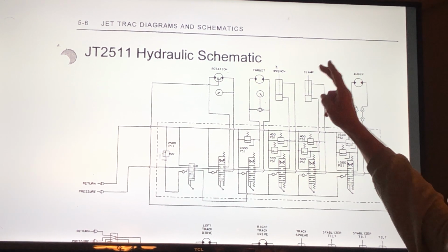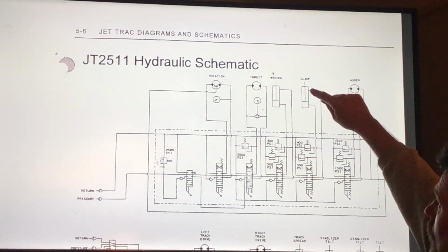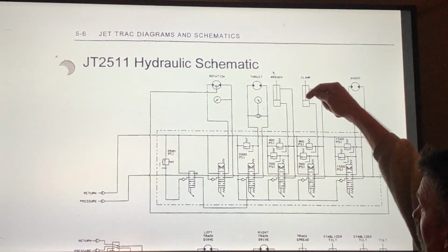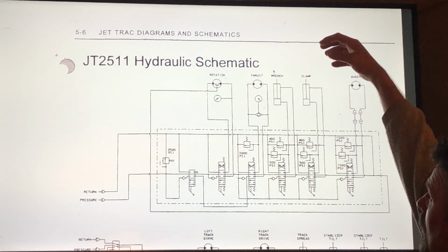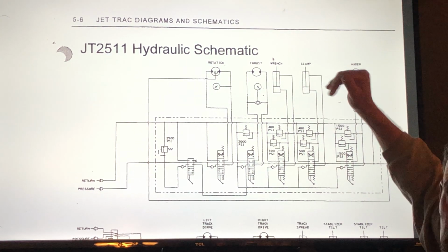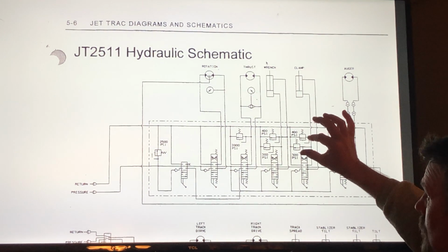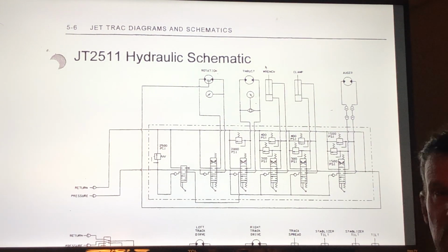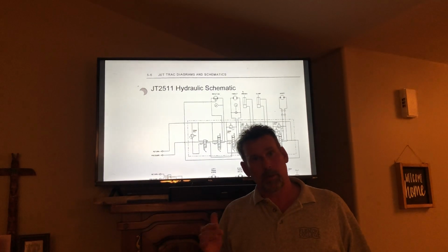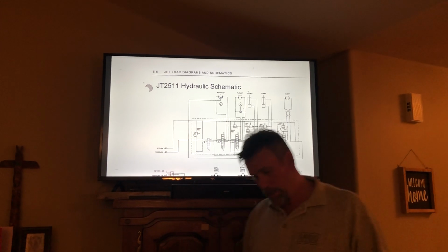So in order to obtain the same force in both directions, we need to put more pressure into the rod side. It has less surface area around the rod, so we need to put more pressure to it so that the force is the same in both directions. Okay, so that's why we have two different pressures, to obtain the same force. And it's just a simple calculation. You plug the numbers in and it tells you what the force will be. So in this case, 300 and 400.